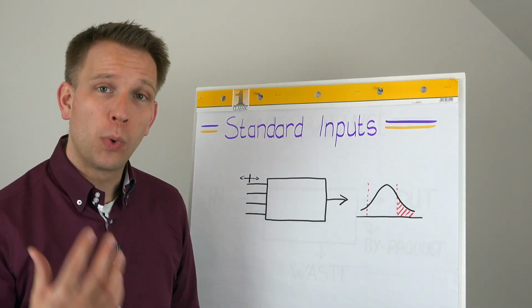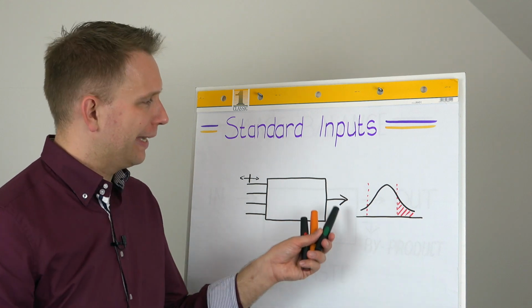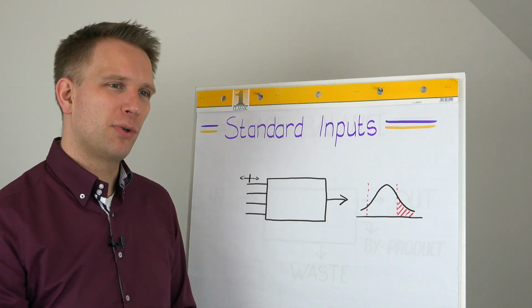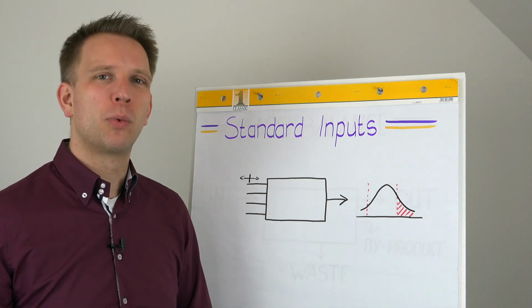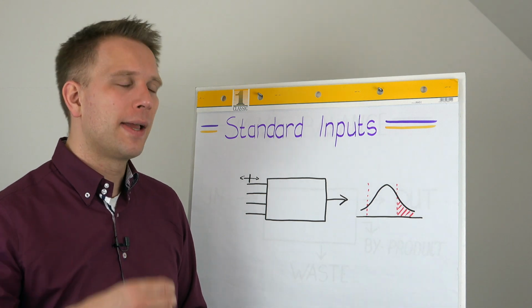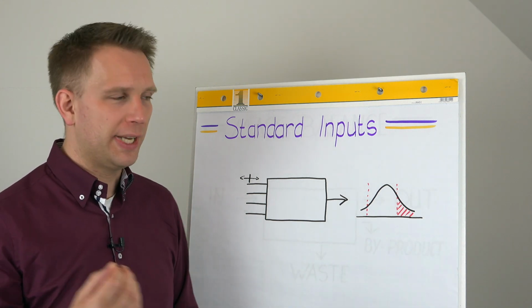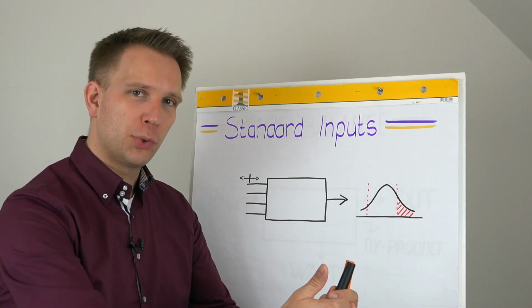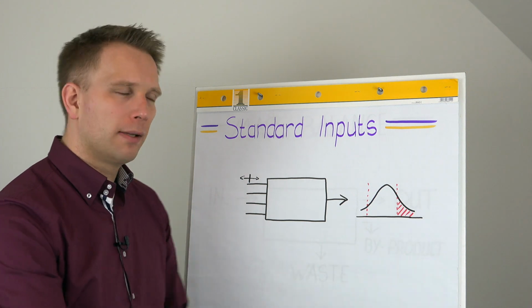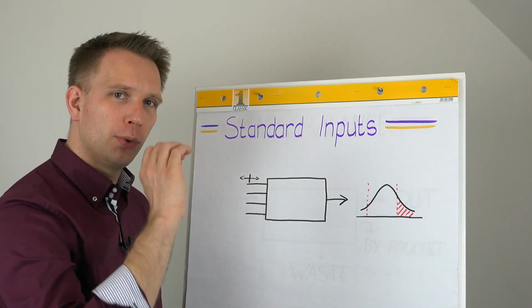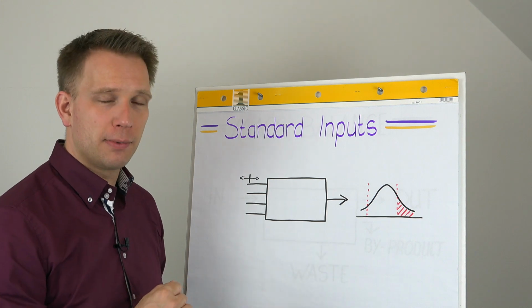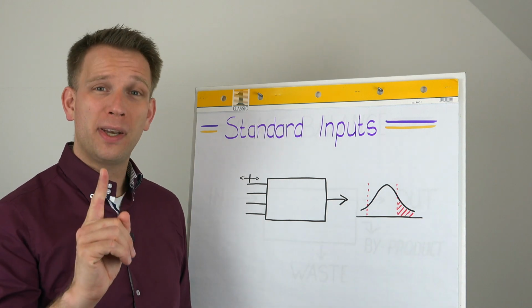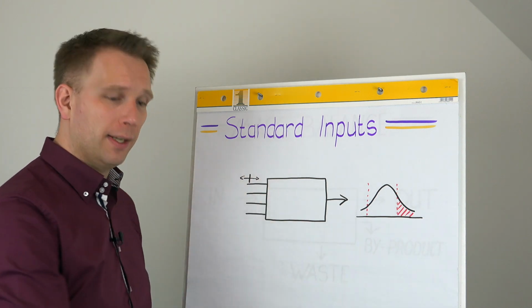Of course, when we know our process, and we also know that there might be some variation in the rest of the process, or maybe the material works a little differently from day to day, we give another clear rule saying when the size of the final product goes up 5 units, we correct it by lowering the temperature from 60 to 58, for instance. But then again, you have a very clear type of calculation. There should only be one set point for anything you set in the process.